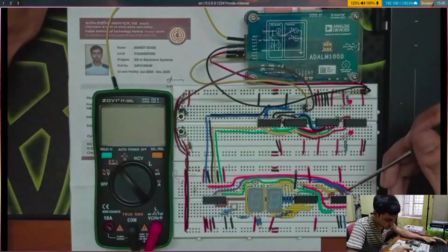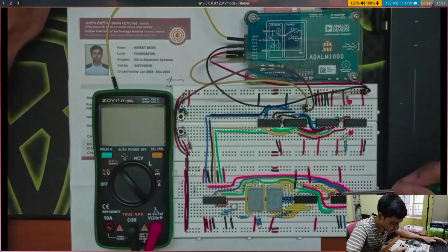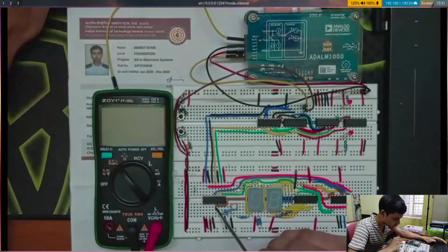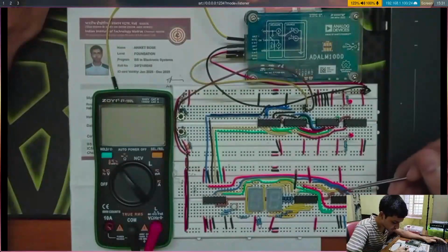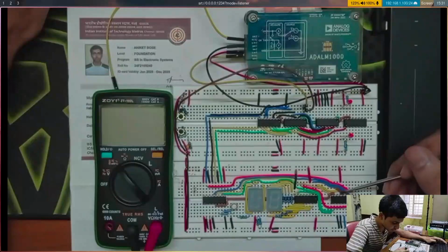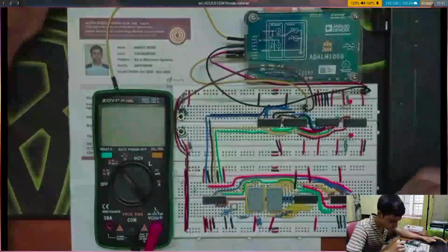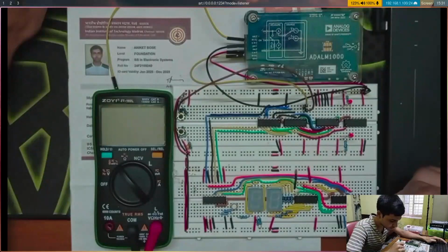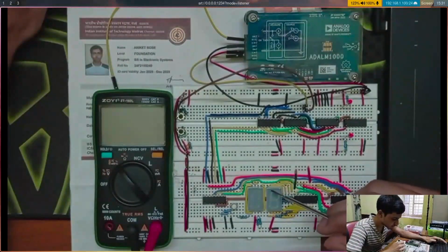And this is connected to an adder. So the adder pins corresponding to B2 and B1 are connected through this A greater than B out. That means whenever the counter value is greater than 9, these two pins, that is B1 and B2, that is 2 to the power 1 plus 2 to the power 2, that is 4 plus 2 will be 6, and this adder will add 6 to whatever the number in the counter is, and then this adder is going to send that number after adding 6 to the segment display, and by doing that we are going to see the proper values in the ones place.